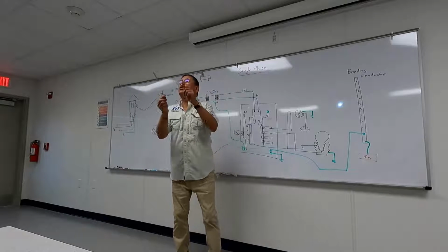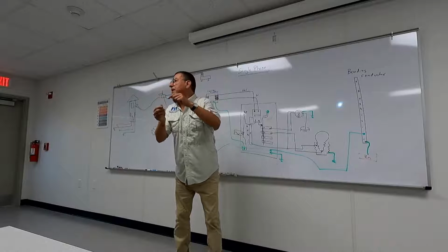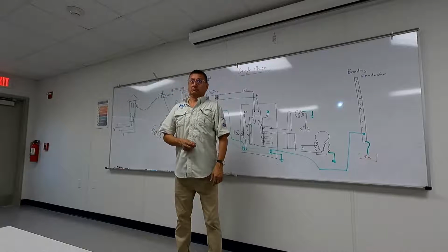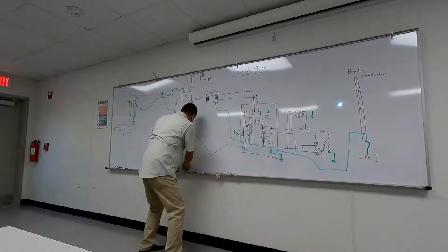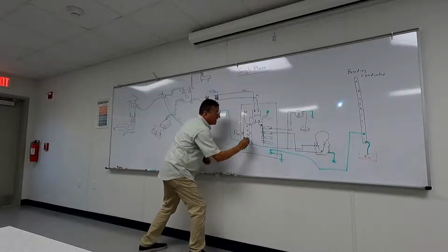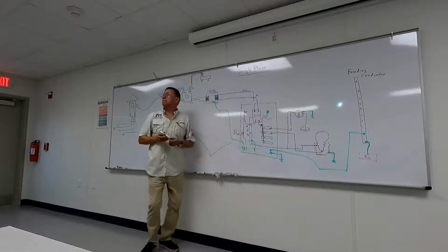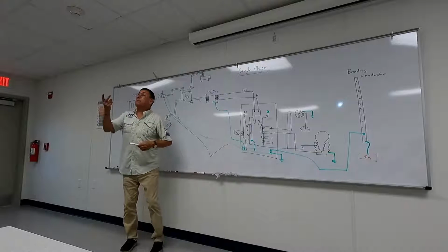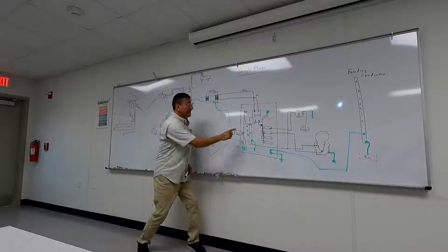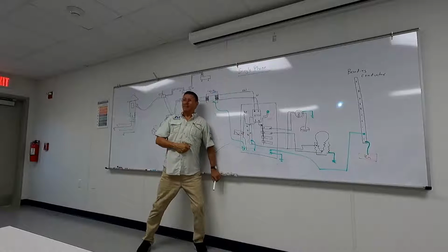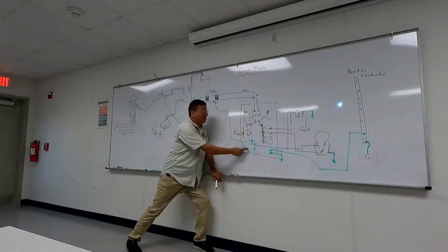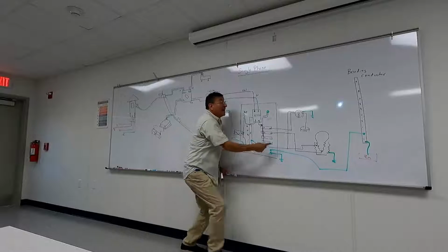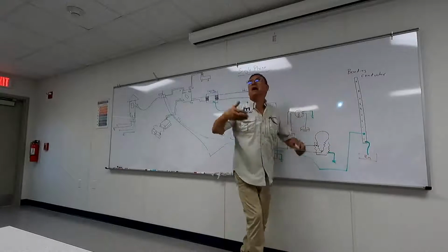And that guy put together the neutral and the ground bus bar. That guy connected this with this because they say it is the same. And now both have reverse polarity. This one is hot. If this is hot right now, this is hot. And I have 120 volts in the bonding.